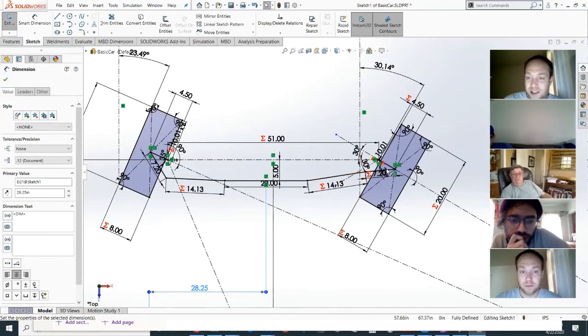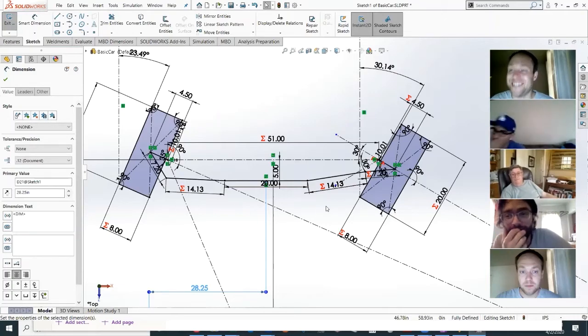Once it gets into a straight line, it won't pull anymore. So if this part kind of starts to kick, like have a more than straight angle, that's physically not going to happen basically. Right. Okay. But that makes it so that if you try to turn back the other way, it'll basically push the tire in the wrong direction. Yeah. So you'll try and turn right and you'll turn left. You'll turn more left. At least the right tire will.